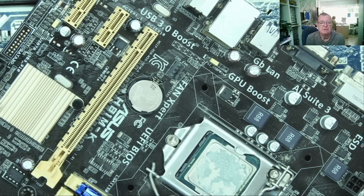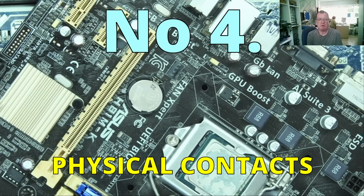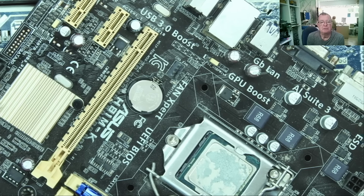And of course, that brings us to number 4, physical contacts. So this covers some obvious things like switches, relays, cables. Sometimes the cables have failed, not the PCB, okay? And some may be less obvious, but IC sockets, especially on old electronics, tend to tarnish, and although it looks okay, you don't have a connection correctly onto all the pins of the IC.